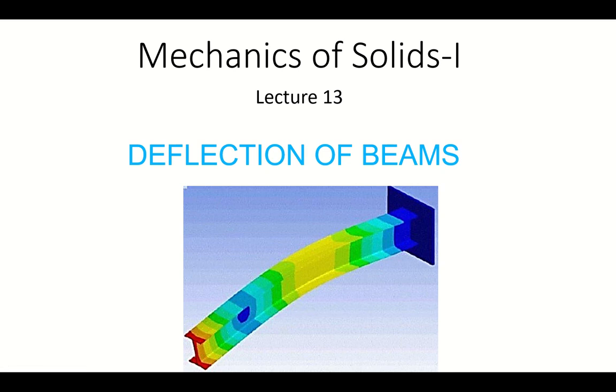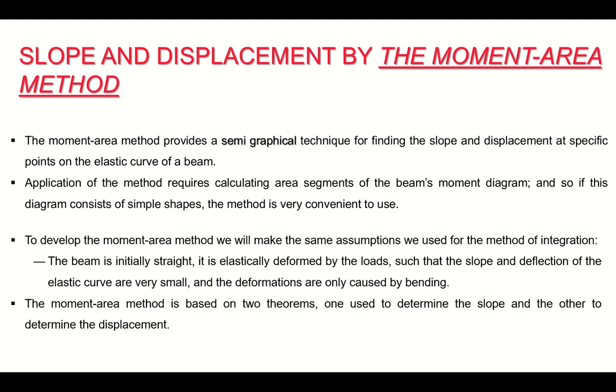Okay guys, welcome back. In this video we will talk about the deflection of beams, but with a different method than the one we discussed in the previous video, which was the double integration method. This method is known as the moment area method, right? And as is evident from its name, the bending moment diagram will be involved in this method, unlike the